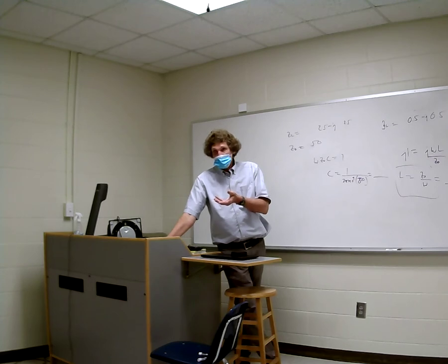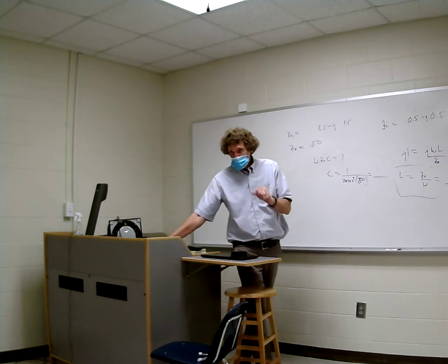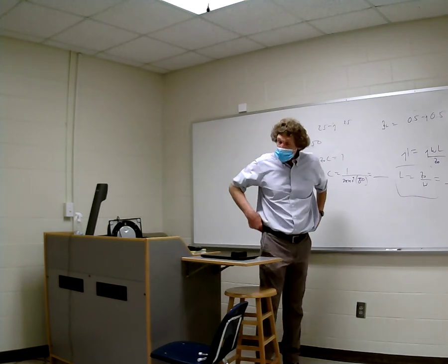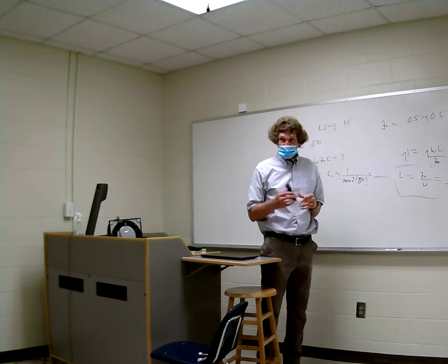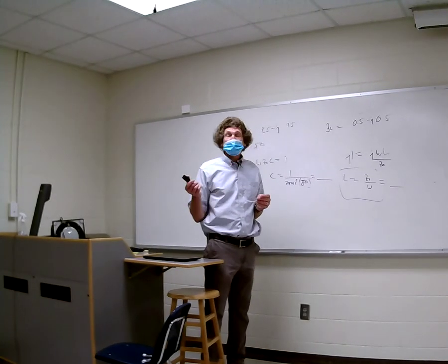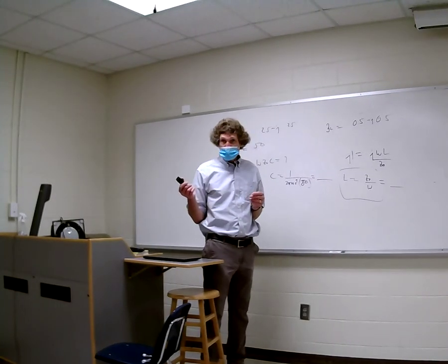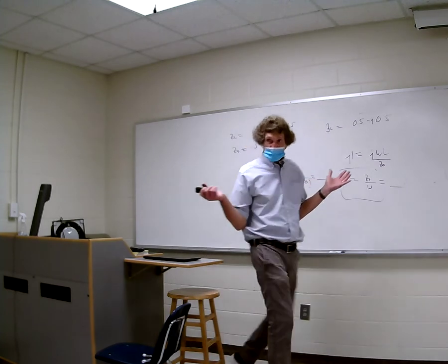But if it's any kind of solid material and you get arc over, it's trashed. It'll never be useful again, because either there's a burnt cord there, it's a short, or that rupture will destroy the actual value of capacitance and change it. And by the way, electrolytic capacitors, when they arc over, or when you drive current in the wrong direction, they blow up. I mean, they're like bombs.